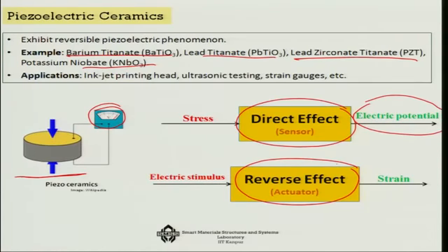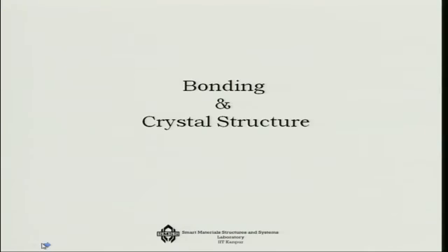That means you apply the electric field and you are going to get strain out of it. The applications are enormous. Some of them are inkjet printing head, ultrasonic testing, strain gauges, various types of sensors, various types of actuators developed using this piezoelectric ceramics. But there are some very special grade of ceramics.